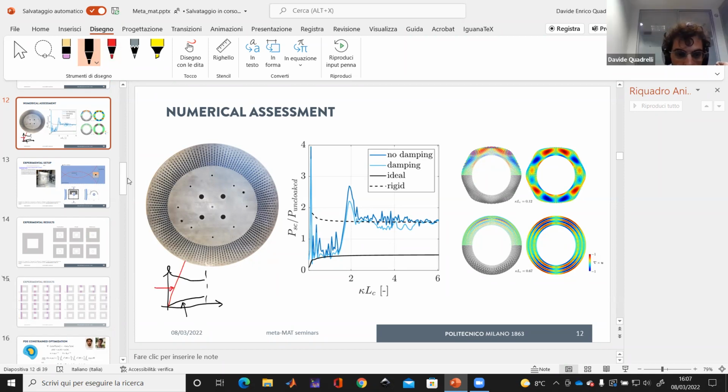What I learned is that because of the great separation of the bulk modulus with respect to the shear modulus, the shear mode gets to a Bragg bandgap, while the wavelength of the longitudinal mode is so big that it is still in the linear regime, more or less. So in this frequency range, you are expecting only longitudinal waves propagating, which is the same behavior as a fluid, which can only sustain propagating longitudinal waves.